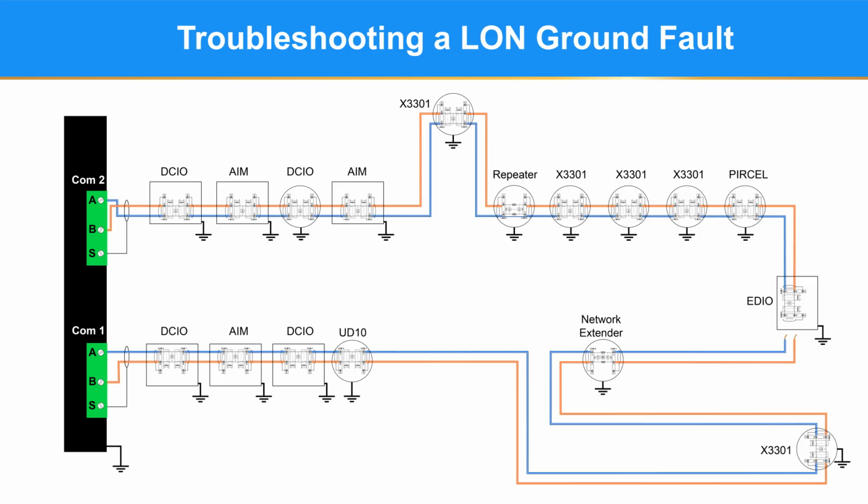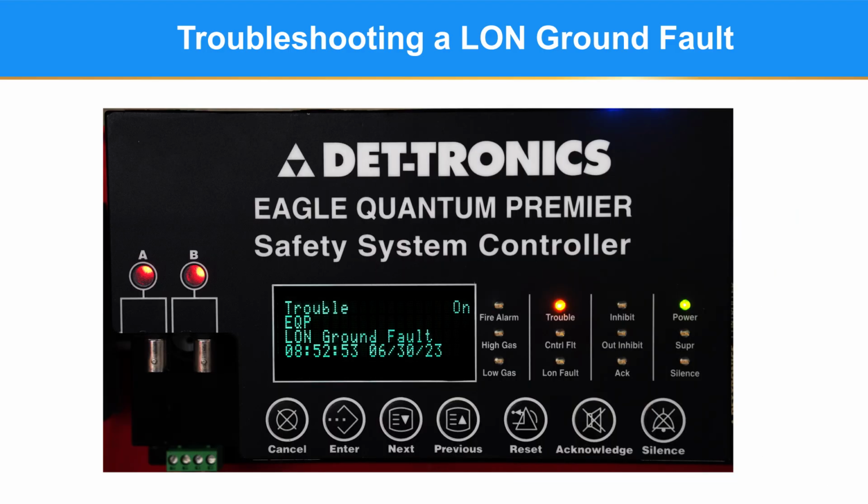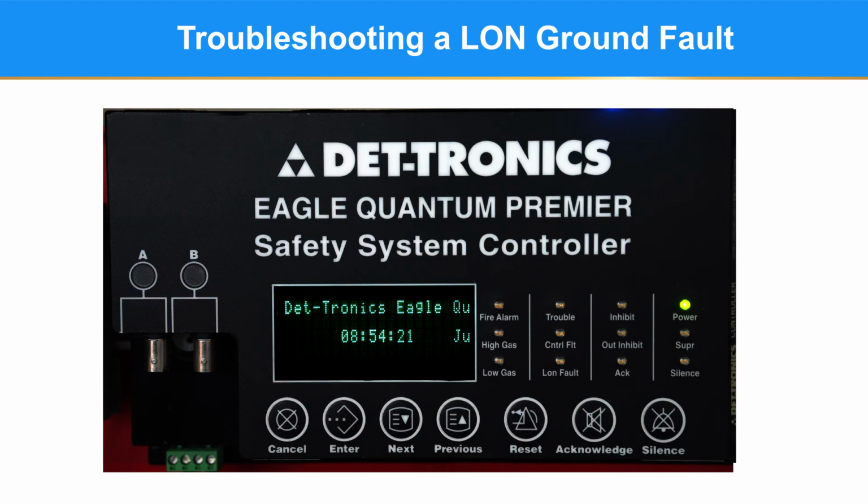You know you have been successful in clearing the LON ground fault when the LON ground fault message disappears from the controller display. You will then need to click on Reset on the controller to clear the LON fault LEDs.